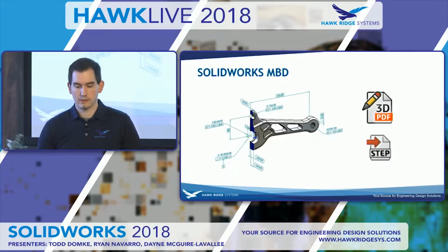So we had a question earlier on, could we export PMI to a STEP file? And STEP 242 is kind of emerging as the new industry standard for neutral file formats that also support PMI. So the answer is with MBD, yes, we can export PMI on a STEP file in STEP 242 format.